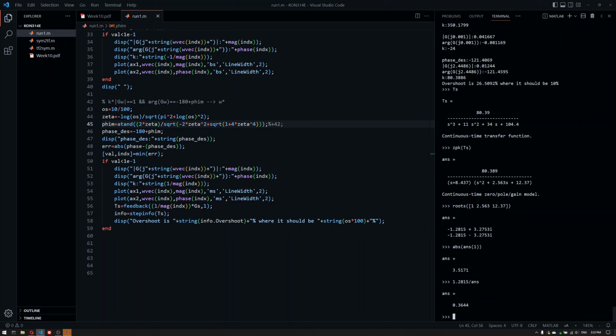Here it's of course not really easy to decompose it into the second order part and a first order part, but maybe you can use the algebraic method and a little bit of calculation with the exact given things here, because you know what your controller is. You can come up with the omega n value, zeta value, and check if it's true or not and why it is working or not. So since we know the time domain version of it, we can just see if it's going to work or not, basically.